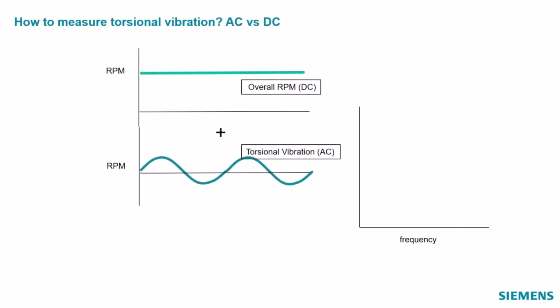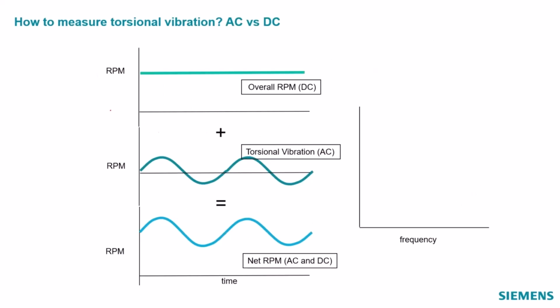What that FFT is doing for us is when we measure the RPM on the other page, I drew something like this where maybe at 1,000 RPM, we have these fluctuations plus or minus. When we do an FFT and we have a constant value, so a constant value like this might be the 1,000 RPM, right? This overall RPM is a combination of both the fluctuating part and the overall RPM.